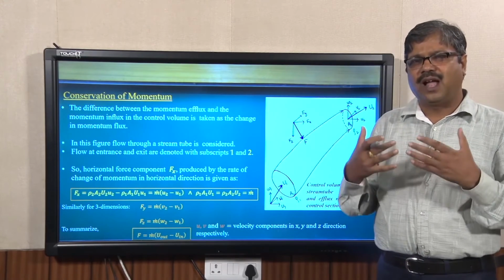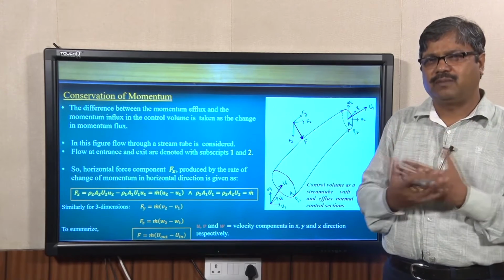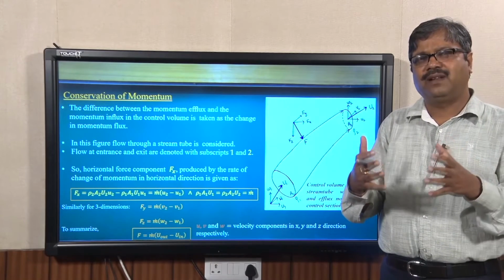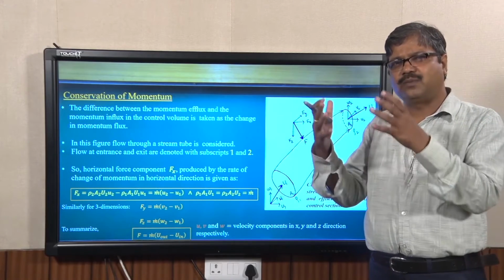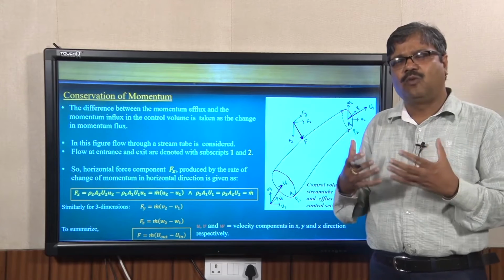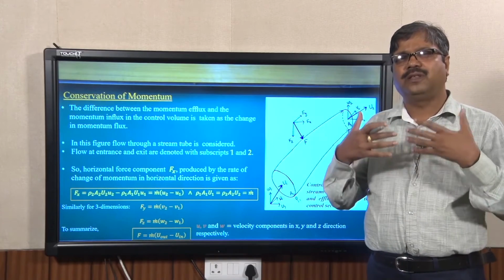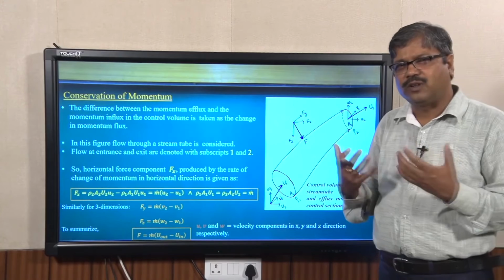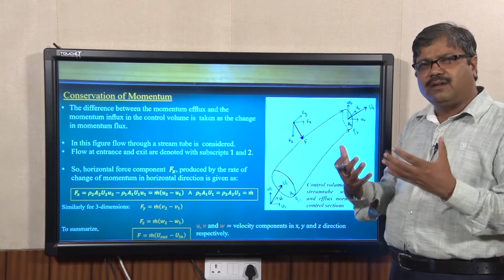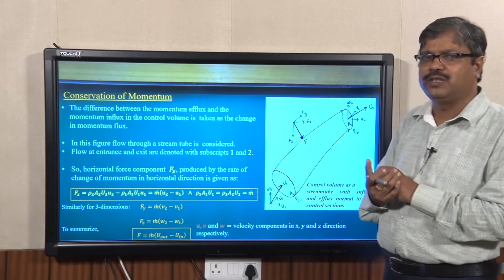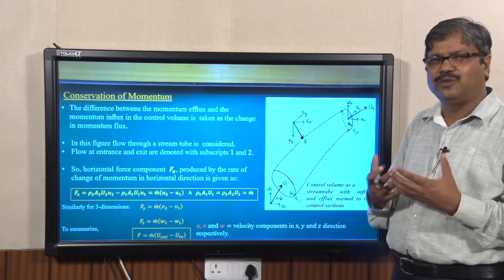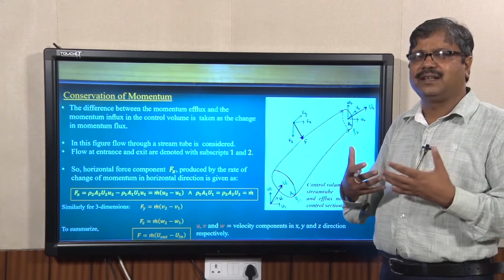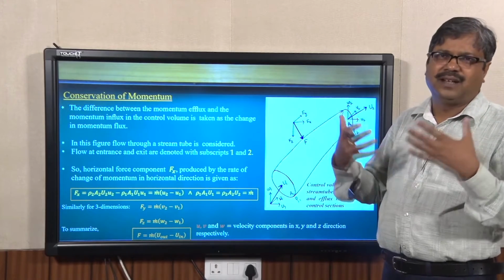Here I will introduce, at an introductory level, the momentum conservation equations on different platforms. One is the control volume at the stream tube level; another is the infinitely small control volume, where we try to find out the velocity field and the pressure field. That derivation gives what are called the Navier-Stokes equations for fluid flow. I introduce these momentum conservations, which we generally use in river flow in very simplified forms, or also in advanced forms considering the velocity field, pressure field and acceleration field.